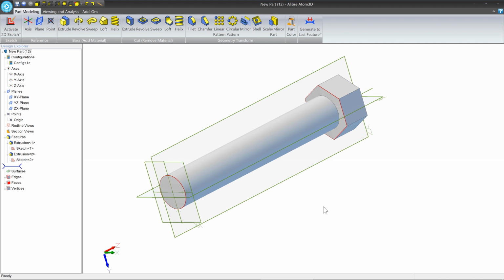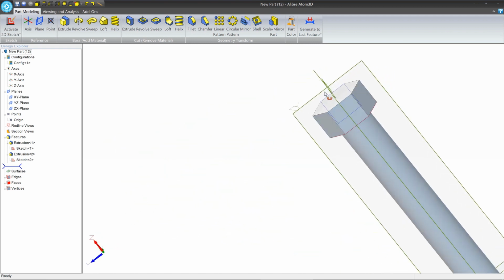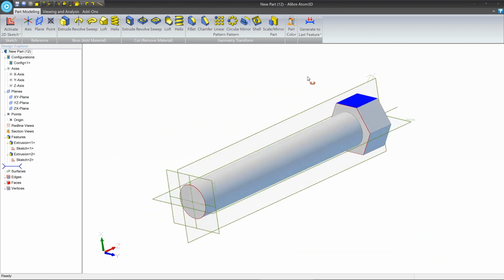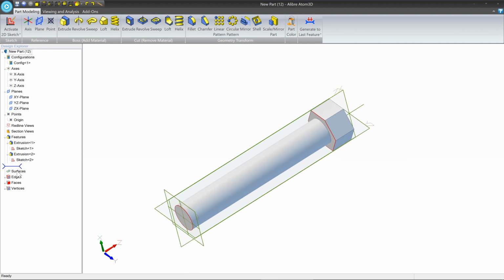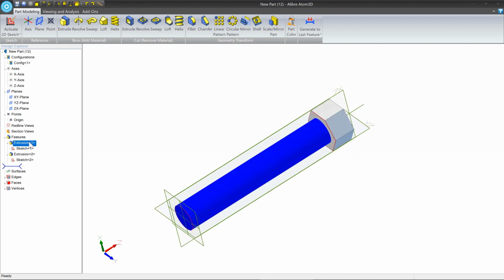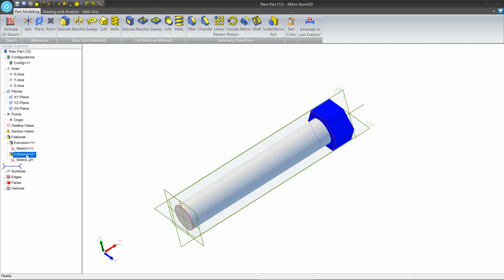So in this lesson, we've covered creating some sketches. We've covered adding dimensions and making a really basic part. Now let's talk a little bit about how do we edit things. So the Design Explorer is filling up with things as we make them. And if we kept on adding more and more things, they would show up here. The Design Explorer is how you access your old sketches, your old features, and it allows you to make changes.